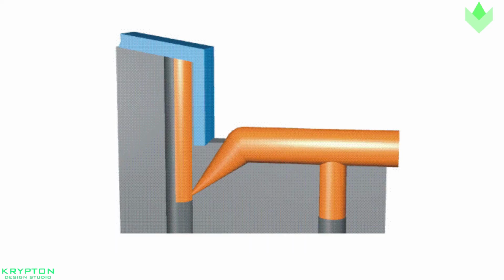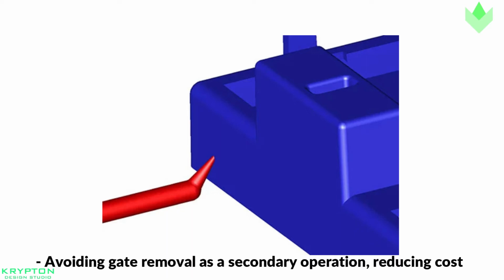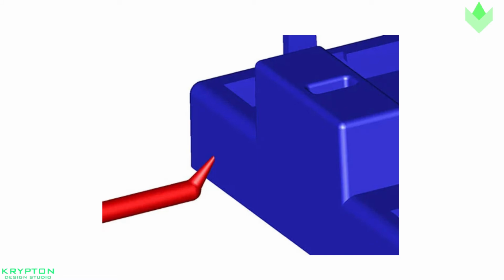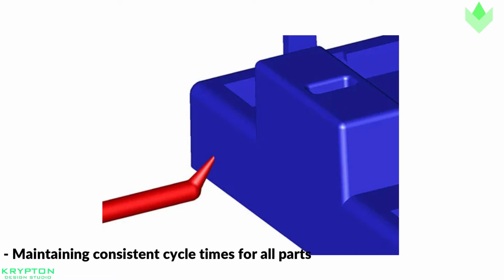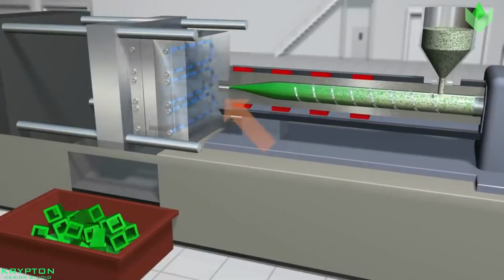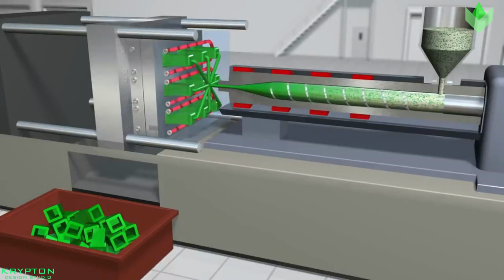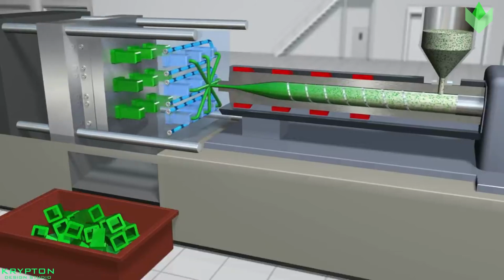Automatically trimmed gates. These types of gates incorporate features in the tool to break or shear the gates when the tool opens to eject the part. Automatically trimmed gates are used for several reasons: avoiding gate removal as a secondary operation, reducing the cost, maintaining consistent cycle times for all parts, minimizing gate scars on the parts. Common gate design. The largest factor to consider when choosing the proper gate type for your application is the gate design.